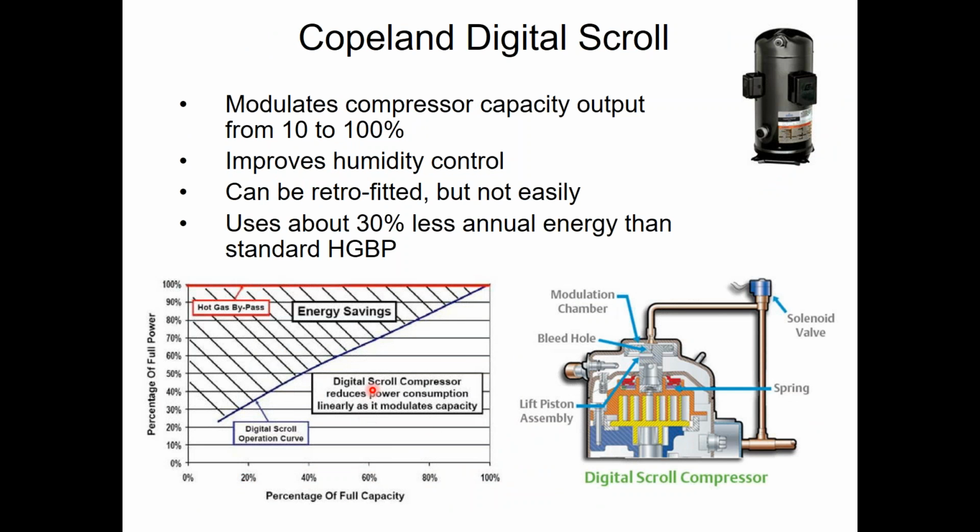In either case, hot gas bypass is not efficient. It's less efficient than anything else you could do with compression. It's just a necessary evil, especially when I have scroll compressors nowadays instead of recips. It's a necessary evil to get those lower stages on.